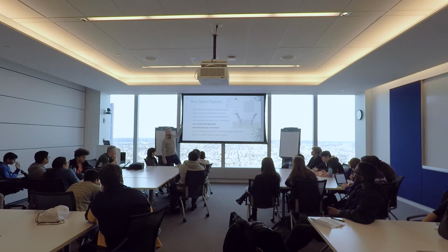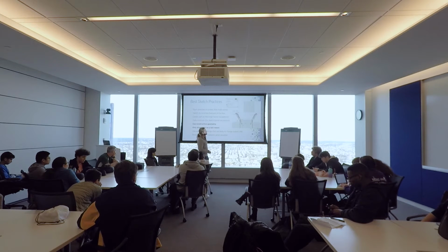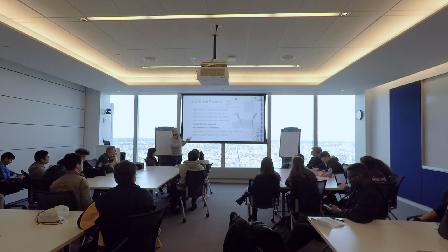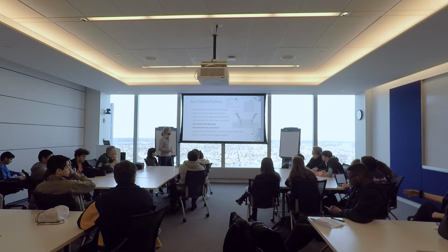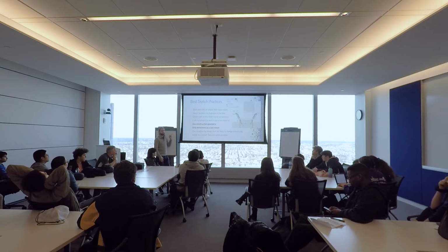Construction geometry. A lot of people don't use construction geometry. I use it all the time, and for those of you that don't know what it is, it's lines in sketches that don't do anything to define the actual bounding box of the feature or the shape, but they just help you align things or set a dimension or give you a layout position or an alignment for something. That stuff is so important to use, and you can very easily switch between construction geometry and regular geometry.